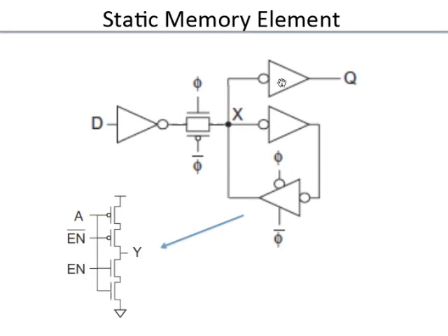You have PMOS and NMOS, both have gate leakages. You have diodes out here. You see these two junctions, they are diodes. You will have leakage through those diodes. In addition, if you have any signals, you will have coupling capacitance to this node. So when those signals switch, charge will get injected. So the value of X is not firmly held. I mean, it can get disturbed easily and then it remains disturbed.